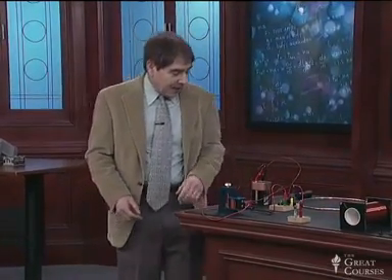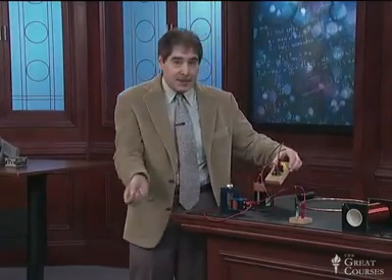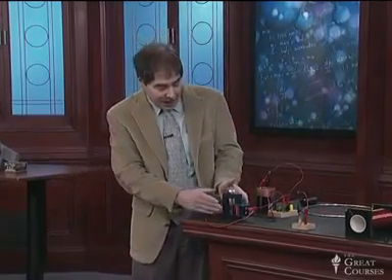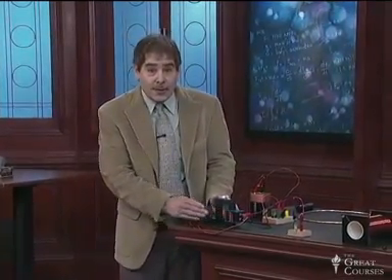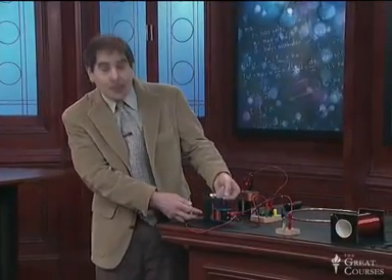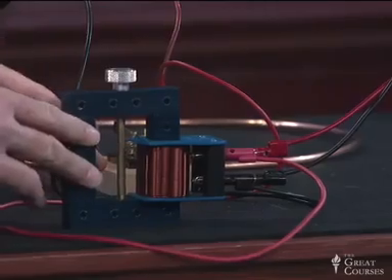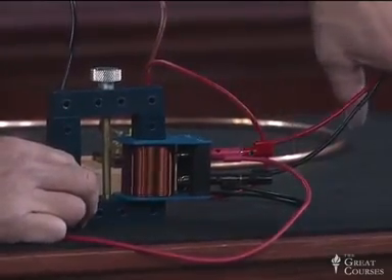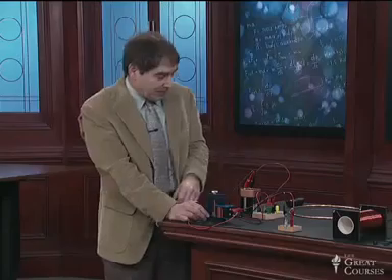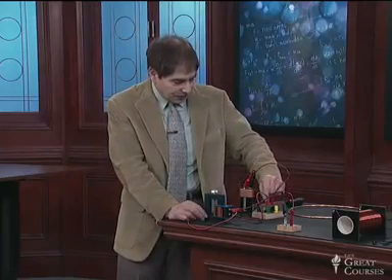Can't hurt me. I have a switch, which is just a metal piece that can make contacts to close a circuit. I have an inductor. This is 1/2 of that transformer I showed you in an earlier lecture. It's just a coil of wire, and to make its inductance bigger, to concentrate its magnetic flux, it's mounted on this iron core. That just increases the inductance. And I have connected across the inductor this light bulb. It's a light bulb that takes about 6 volts or a little more to glow to full brightness.